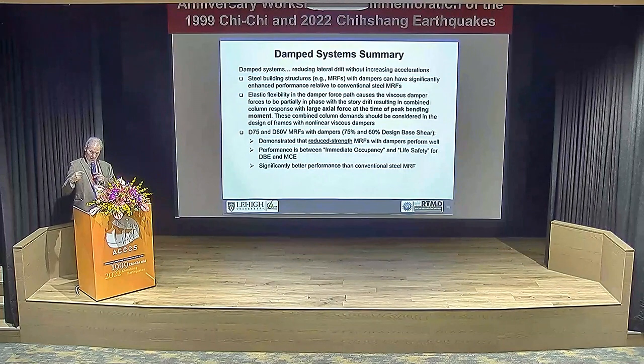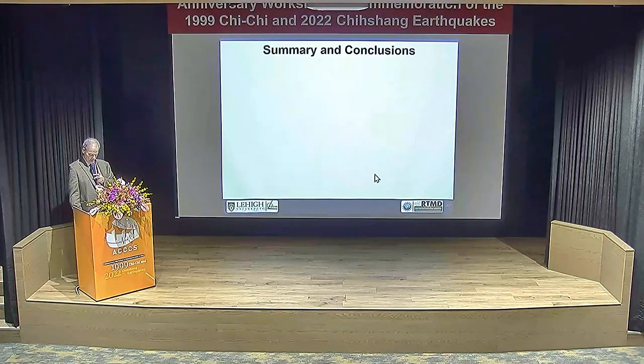And if you have this kind of performance level, in the US we look at immediate occupancy and life safety and collapse. These perform immediate, and if you look at the MC, maybe someplace between immediate and life safety there, but they performed well. Significant better performance than conventional MRS without the dampers.